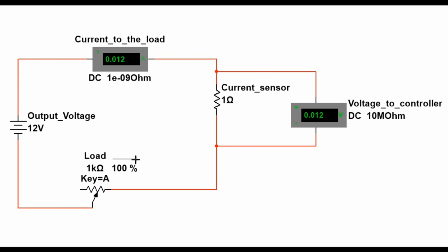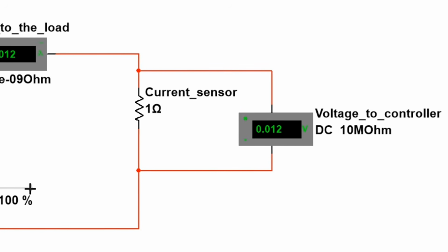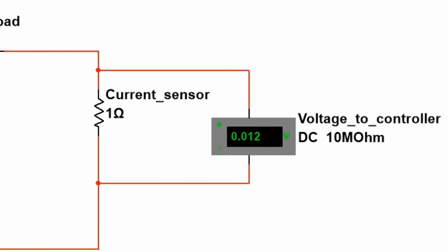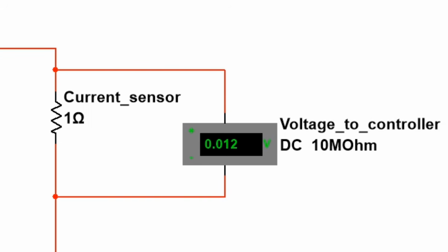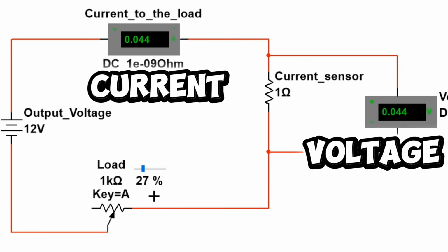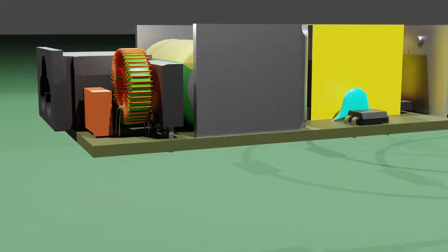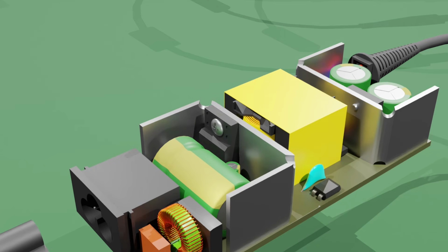To protect the PC from overcurrent, which would cause a fire, the current into the transformer must flow through a very low value resistor around 2 ohms. The voltage across that resistor is measured by the controller. When the current flowing through the transformer suddenly increases, the voltage across that resistor also increases. This is true by Ohm's law. The IC detects it and immediately turns off the MOSFET switch. This protects you and your PC from an electric fire.